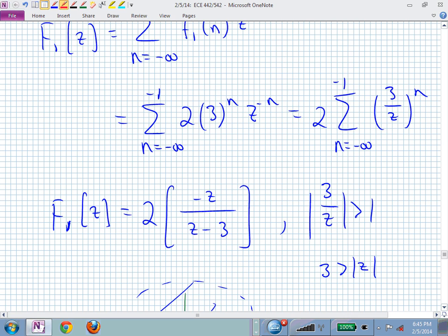Then you can inverse Z transform without knowing explicitly what the region of convergence is. They just told it to you. They hinted it to you. It's a causal sequence. Okay, I know. Means it's unbounded in extent, the region of convergence. That means all the poles are lying inside the region of convergence. Then stability can be determined by where the poles are. And if they gave you the other case, you could also determine based on where your poles are.